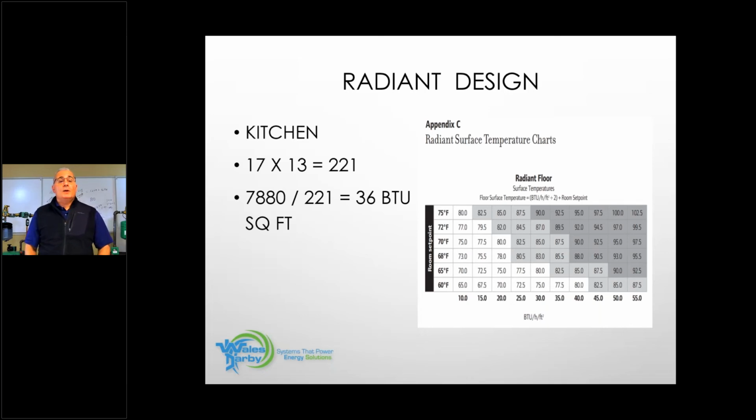Radiant heat is wonderful heating, but if we don't do it right, we could screw it up and have a terrible system. So we want to make sure, based on whatever material the floor is going to be finished in, whether it's tile or wood, or if it's going to be a friendly carpet and pad for that type of install, that we don't go over surface temperatures that could cause discomfort.